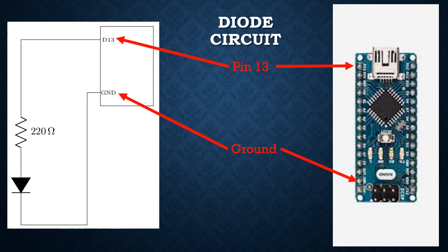Okay, the last thing you want to connect is a wire, the wire that's on the lower end of the diode. You want to run that wire from some hole in row 25, let's say 25E, all the way back up to a hole that's just to the left of the ground pin. I hope that wasn't too confusing.